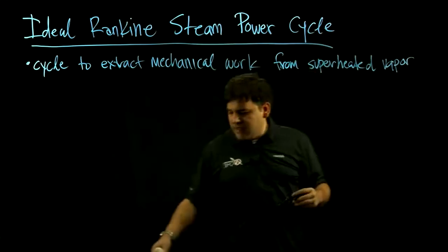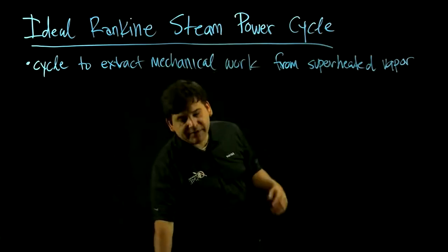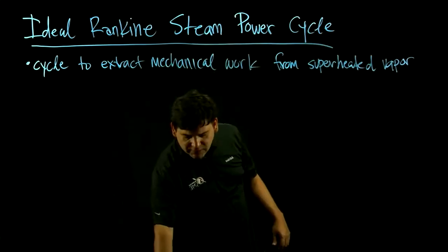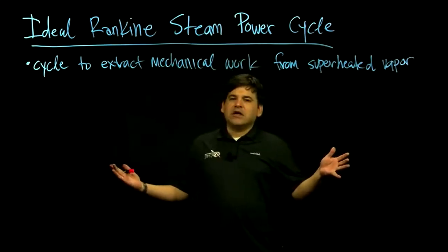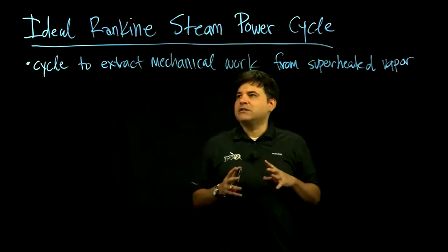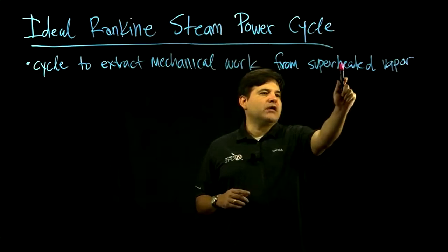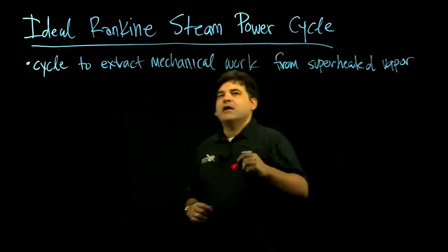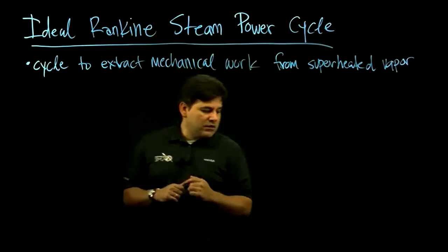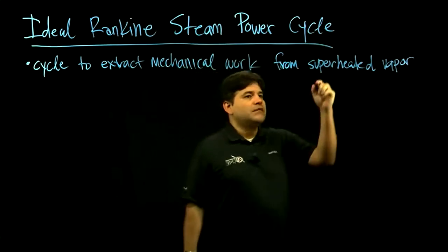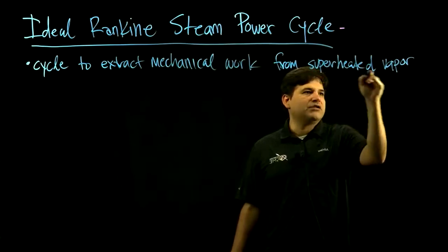It's water in its vapor state at high temperature and high pressure relative to our ambient conditions. Water is liquid in most parts of the earth unless you're frozen. There's some in the air at all times, trace amounts, but if you really heat up this system to high temperatures and within some range of pressures, you'll get all gas phase, superheated. And the boiler part of this cycle is where you get this energy to bring water from liquid to superheated vapor.